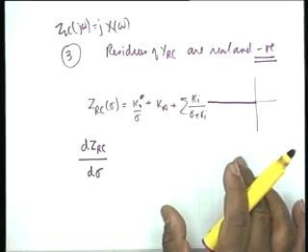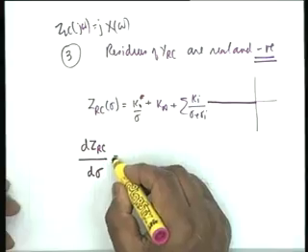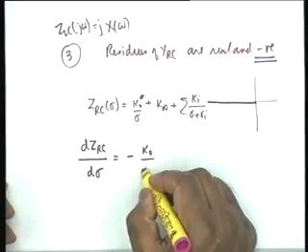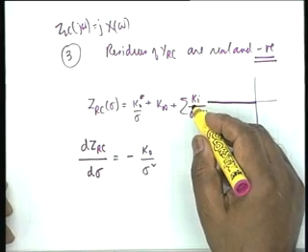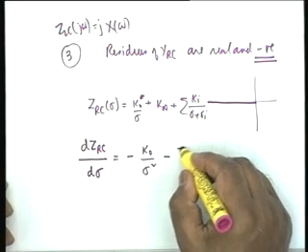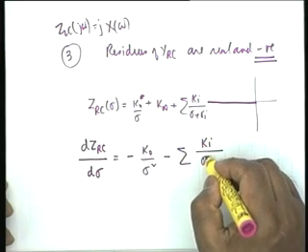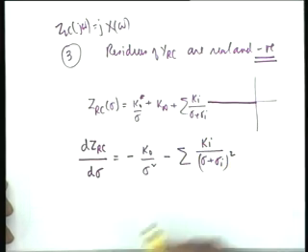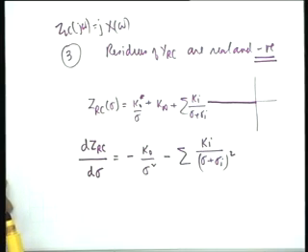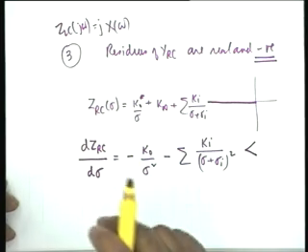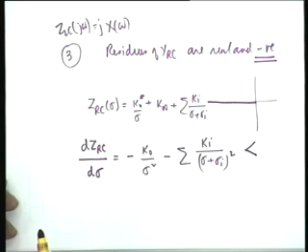What is the objection about this? I have simply put s equal to sigma, nothing else. Now, if I differentiate, notice that it would be minus k 0 by sigma squared, k infinity differentiated would give 0, and what about this term? It would be minus summation k i divided by sigma plus sigma i whole squared. And you see that each of these quantities are positive, and therefore this slope of ZRC on the real axis would be strictly negative.